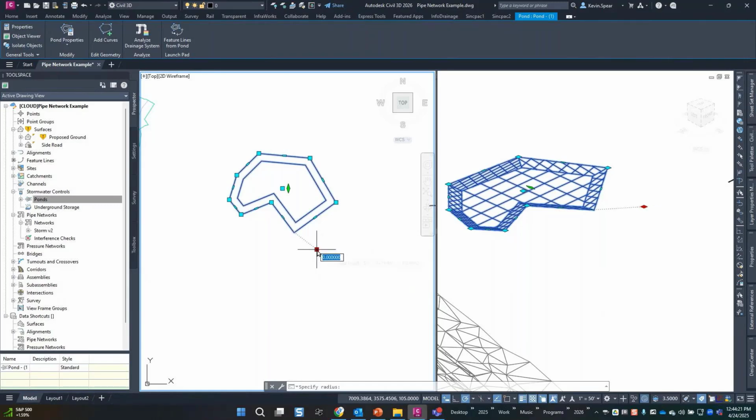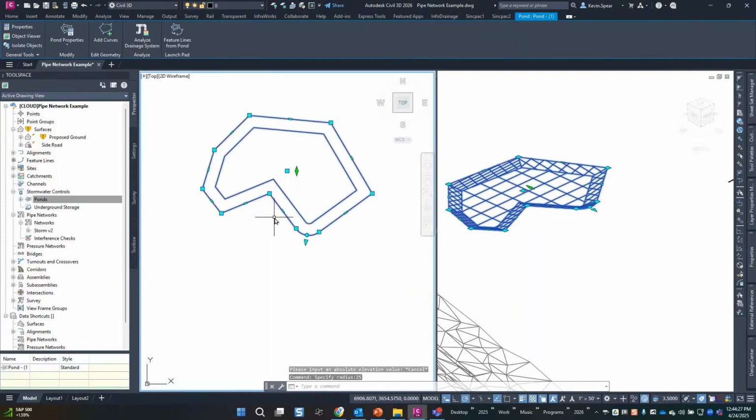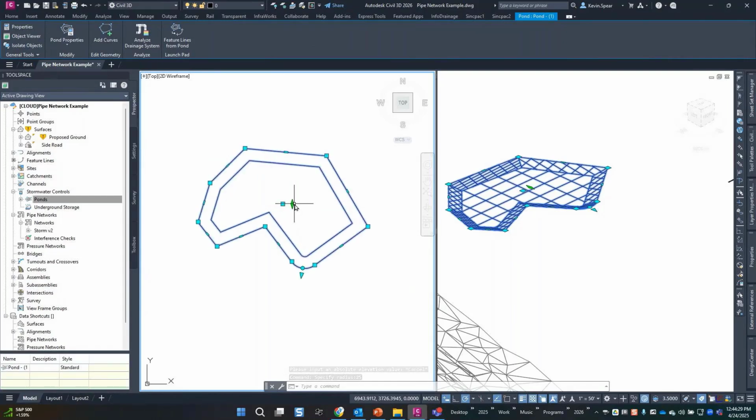So if I add a curve, let's say 25 feet, there's my 25-foot curve. So there's lots of choices there. What about on the midpoint? Same thing, stretch or add. So we'll just throw a few of these in here real quick, just for the sake of watching it do whatever there, right?